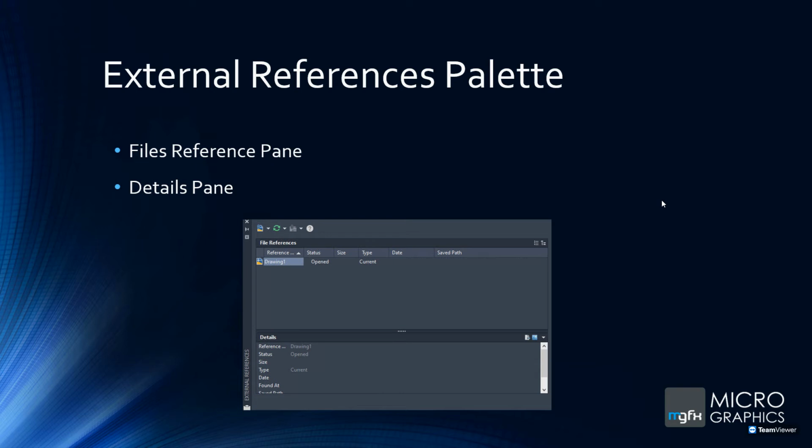Okay, so just another slide about the Xref palette. At the top, obviously, is your files reference pane, so that's where all your drawings are. And if you select any of the Xref files, or even your host file, at the bottom is your details pane. It will tell you what's happening with it, where it is, the date you Xref'd it, etc.